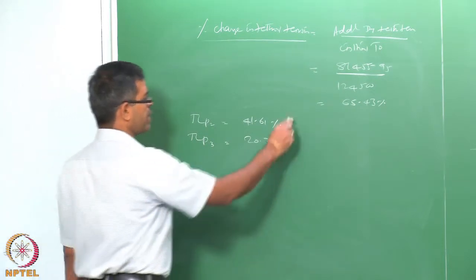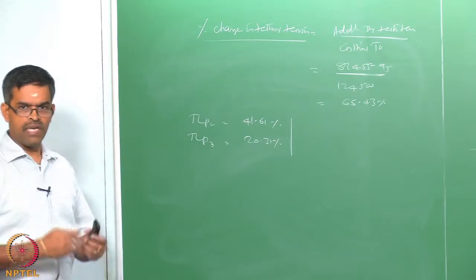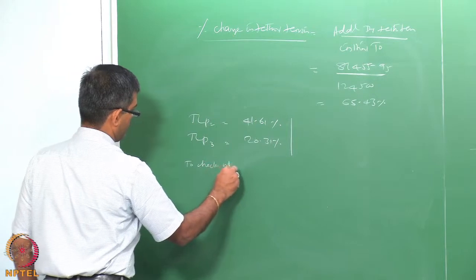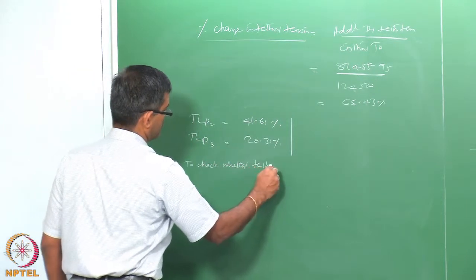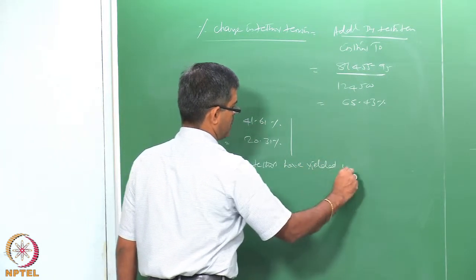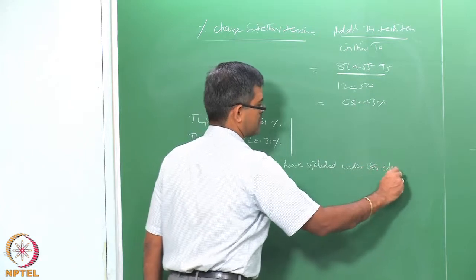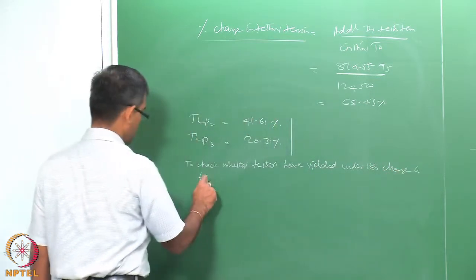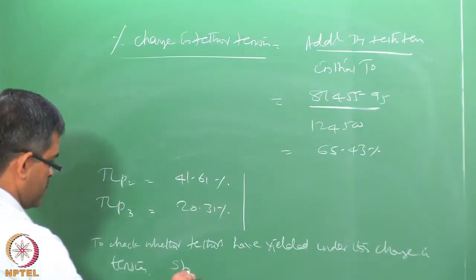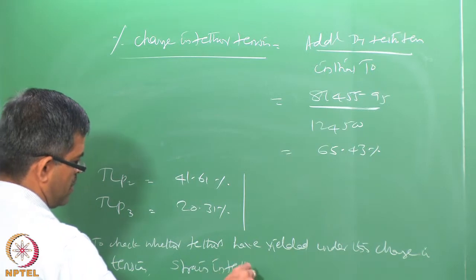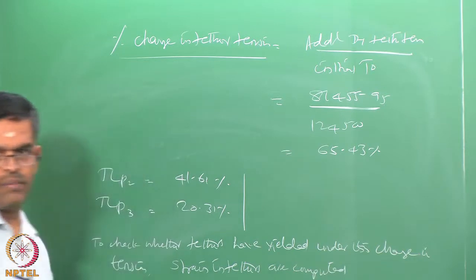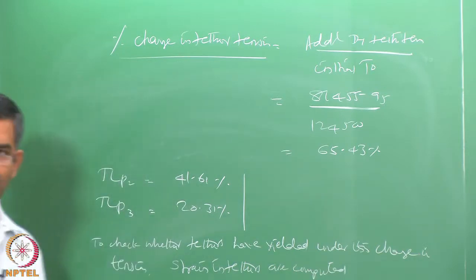Now, one is also worried whether the tethers have yielded or not. So, to check whether tethers have yielded under this change in tension, we have also computed the strain in tethers, and the table shows the values of strain also.